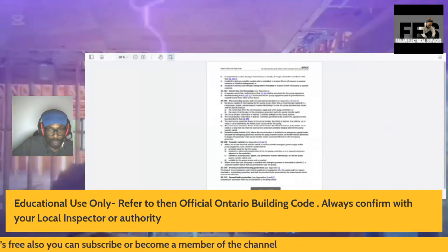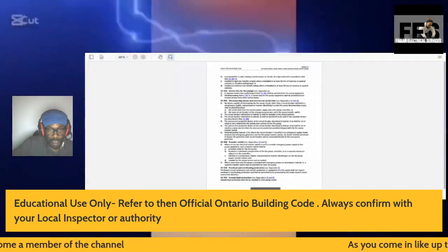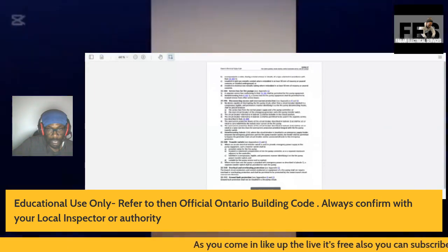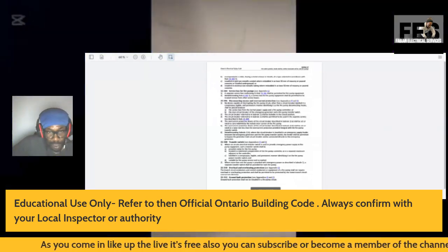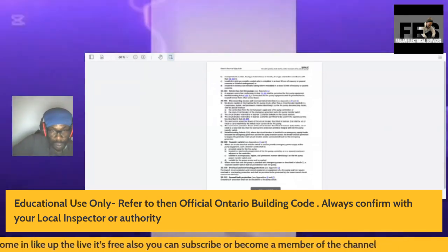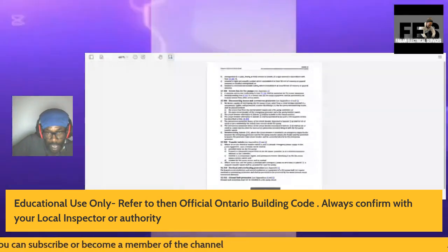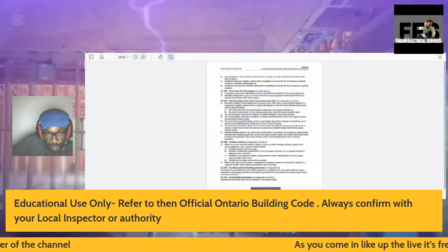Disconnecting means and overcurrent protection. No device capable of interrupting the fire pump circuit other than a circuit breaker labeled in a conspicuous, legible and permanent manner, identifying it as the fire pump.